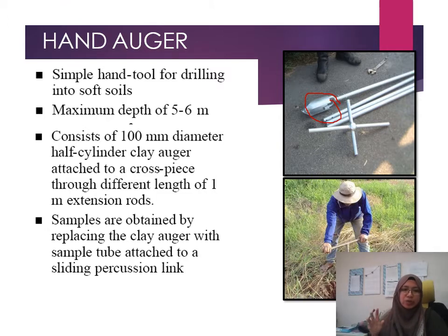Another procedure is using a sampler. So we replace the clay auger with a sample tube attached to a sliding percussion link. So this is the sampler.